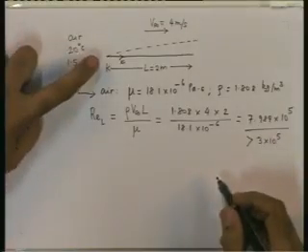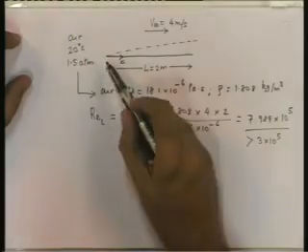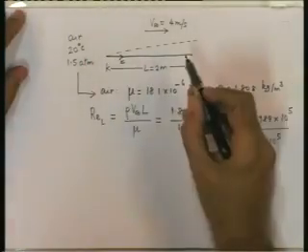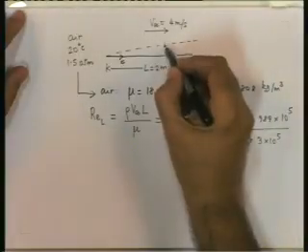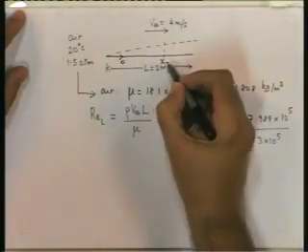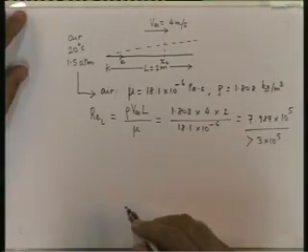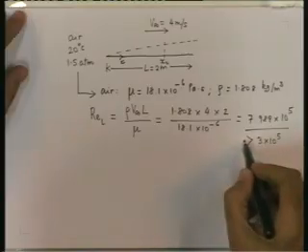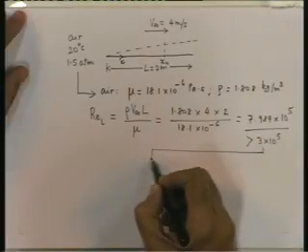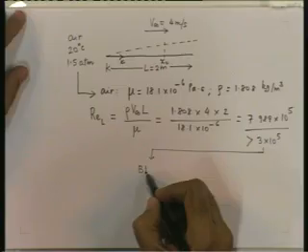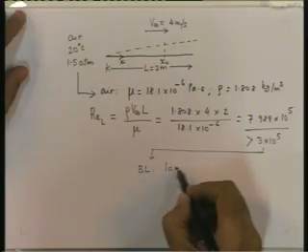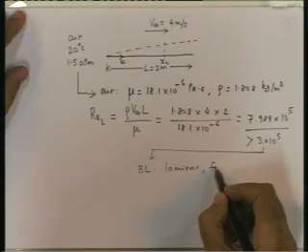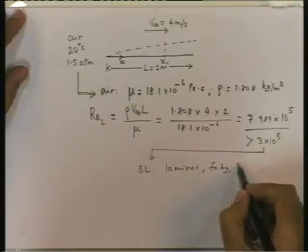Since our leading edge is smooth and sharp, we expect the boundary layer to begin as a laminar boundary layer, and at some place in between, represented by an XC to be determined, it will become turbulent. So this implies that the boundary layer is laminar followed by turbulent.